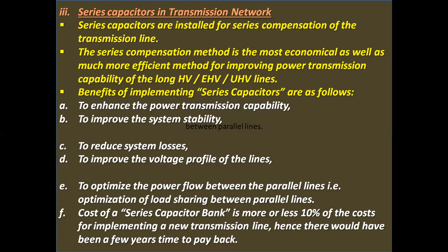E, to optimize the power flow between the parallel lines, that is optimization of load sharing between parallel lines. F, cost of a series capacitor bank is more or less 10% of the costs for implementing a new transmission line. Hence, there would have been a few years' time to pay back.